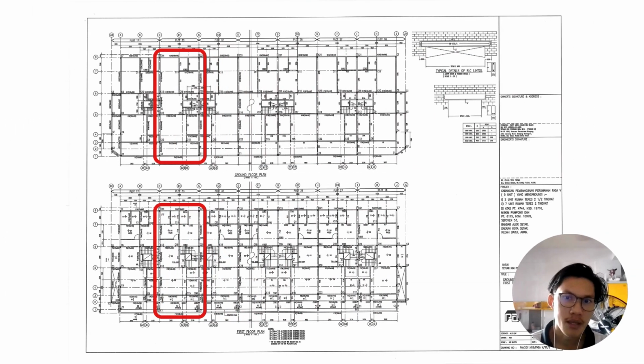Next is the modular plan. So this slide shows the modular plan, which is a critical drawing in the IBS design. The house layout is divided based on standard modular grid that ensures the wall, slab and openings align with the IBS component size. This approach minimizes material wastage, improves the manufacturing accuracy and increases the construction efficiency.